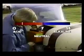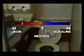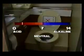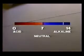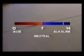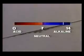In addition, sulfuric acid found in volcanic dust, ozone from electrical discharges, and even human and animal waste, which contain uric acid, are very corrosive to metals. At the other end of the pH scale, alkalis aren't generally as harsh as acids, but will still attack aluminum and magnesium alloys. Alkaline chemical cleaners are particularly corrosive to aluminum.